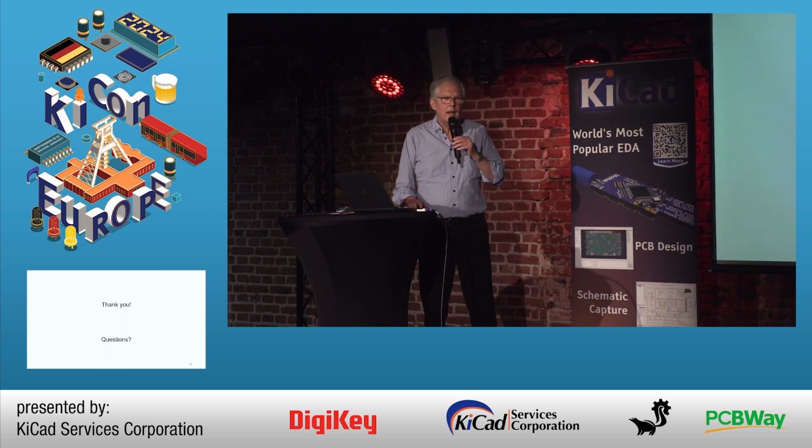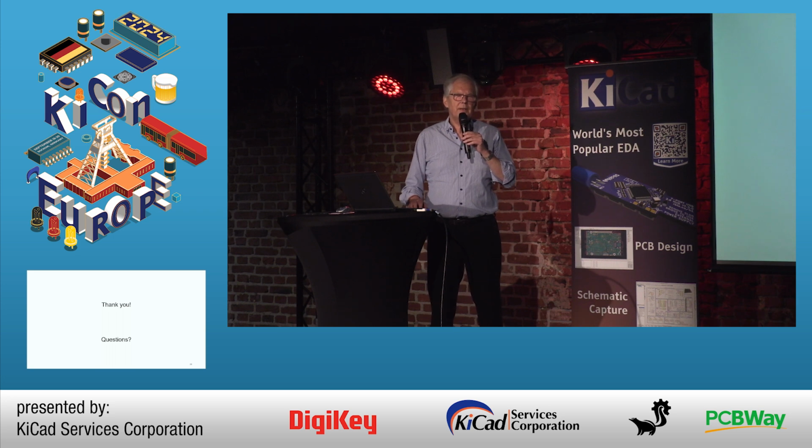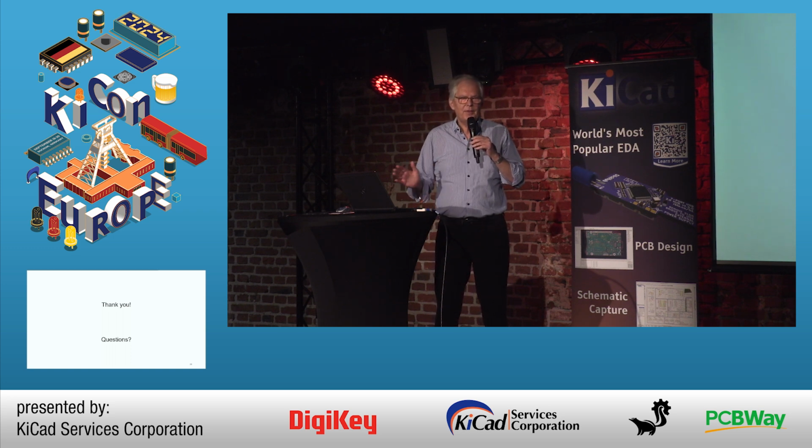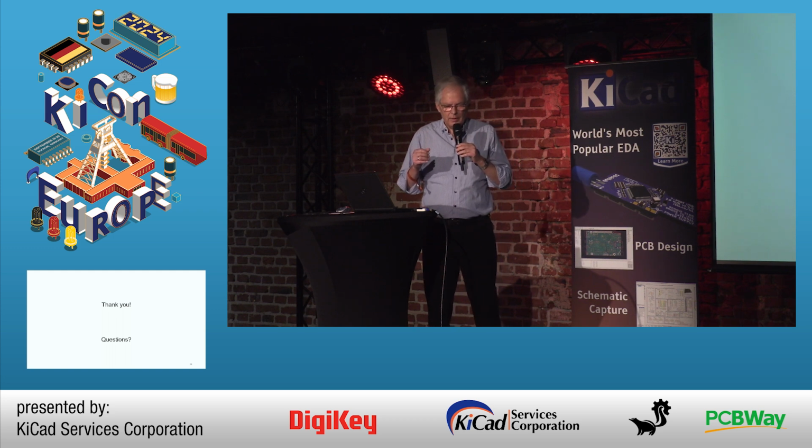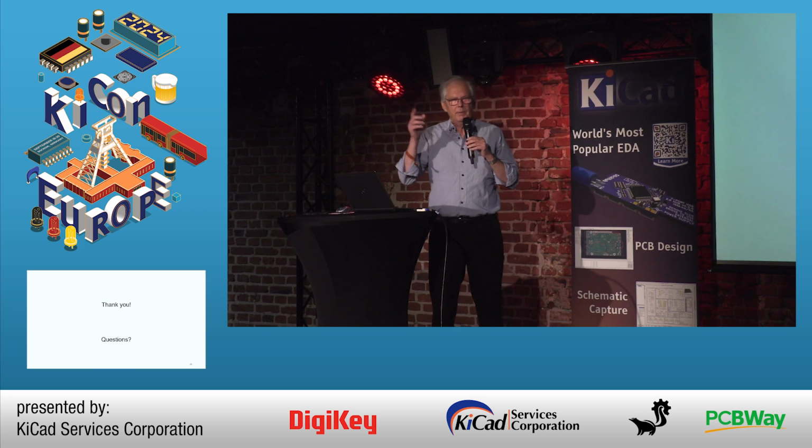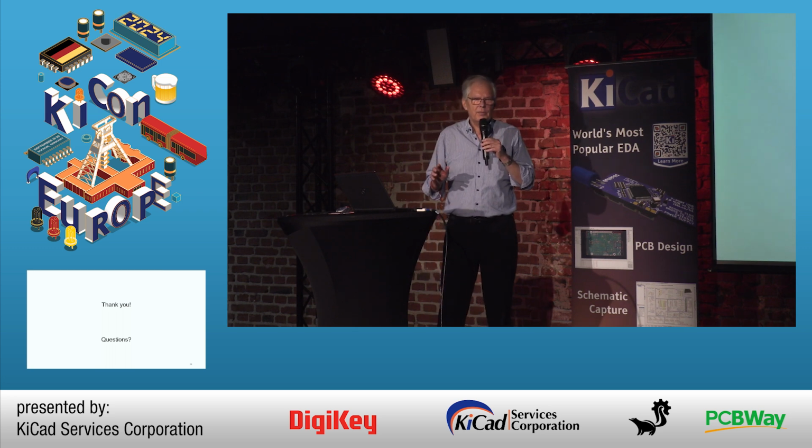Thanks. There is no basic limit because the mathematics is the same. It depends very strongly on the device models, and on the interfaces between the devices. If you talk about integrated circuits, for example, we are now working together with the IHP institution in Frankfurt-Oder, and they develop bipolar transistors running up to 450 or 500 gigahertz. We have the models for this, and it can be done.